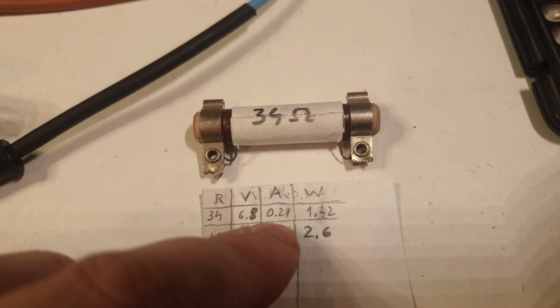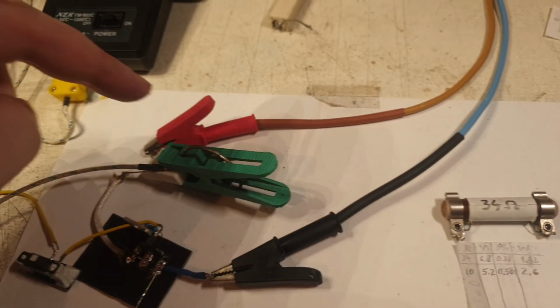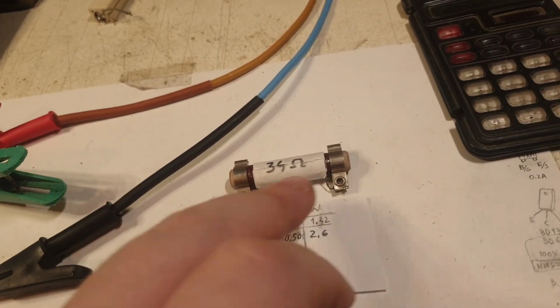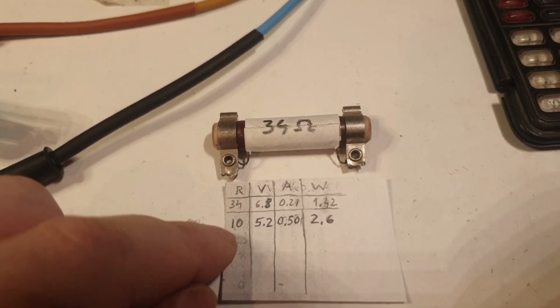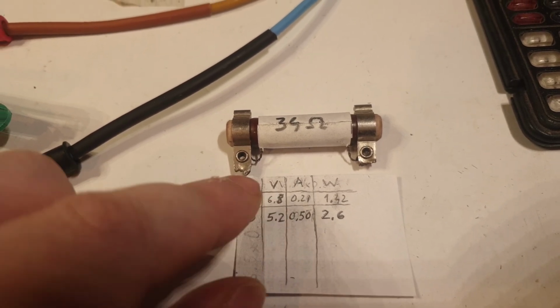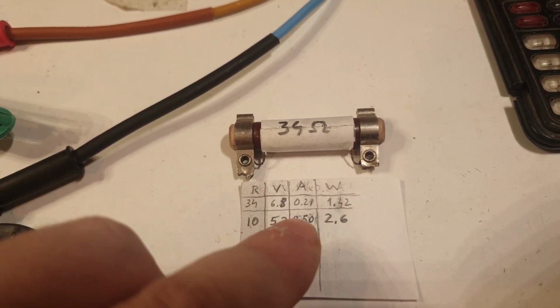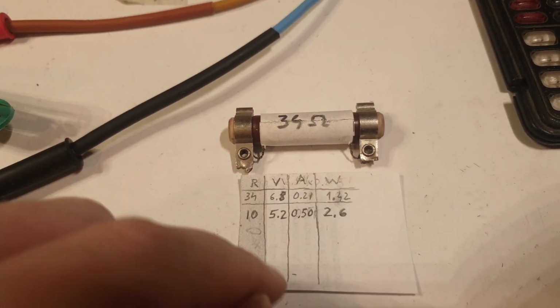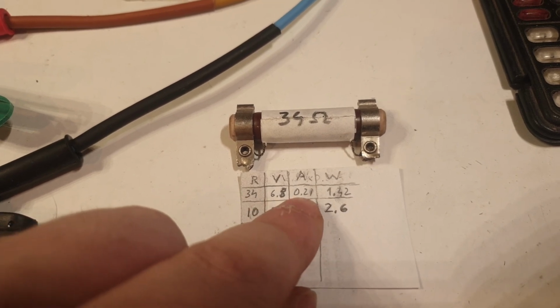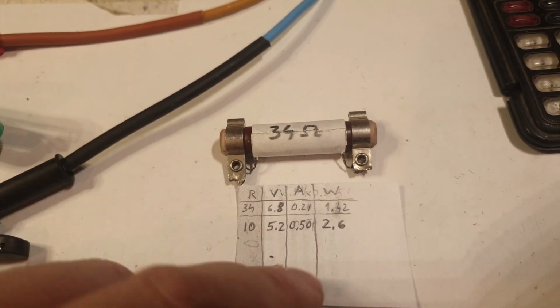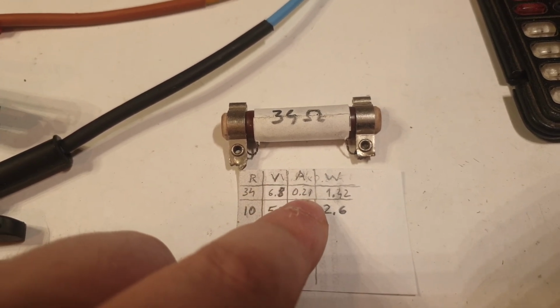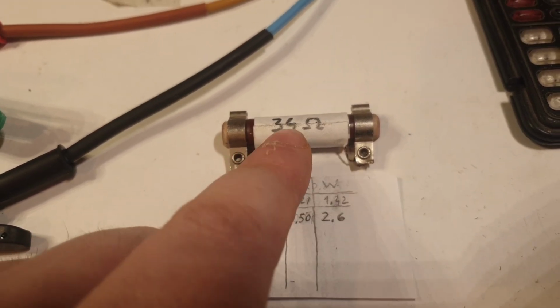This is another way to test a resistor using your power supply directly. I hooked these two alligator clips directly here and here, and not with this circuit. So directly there, and I read those values. At 3.4 volts, I set the voltage to 3.4 volts, and I get exactly 0.1 amps. And here is very close to it. It's 34 point something, maybe 34.5 ohms, so that's why I'm getting 0.21 there. It should have been 0.2 exactly if it was exactly 34 ohms.